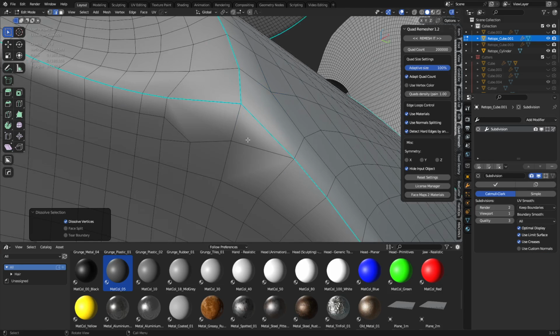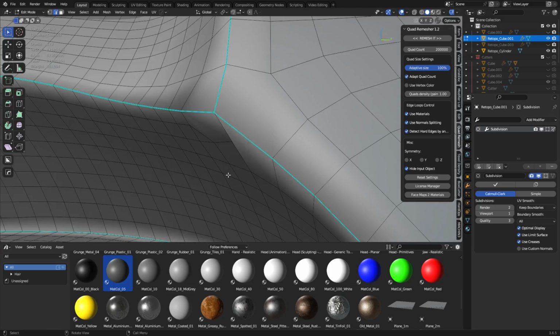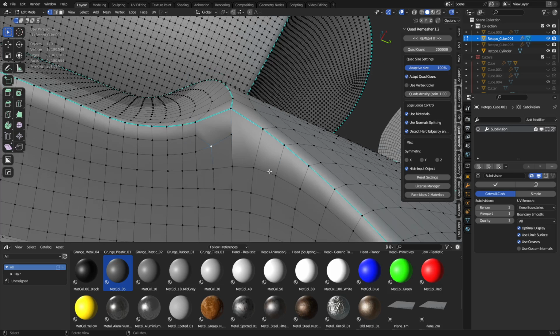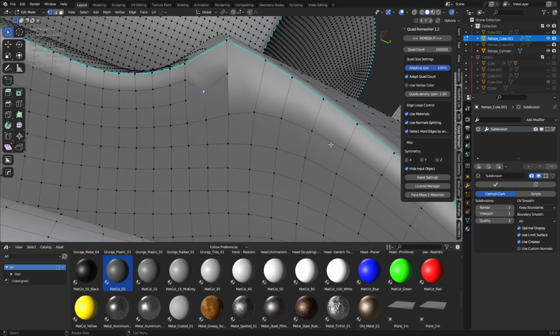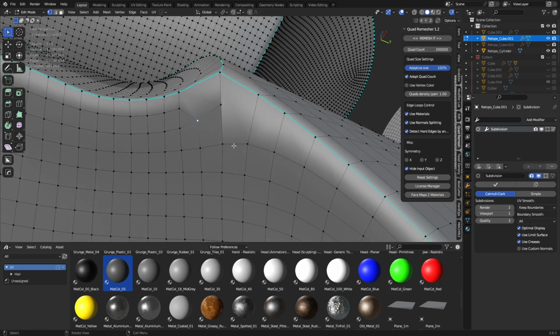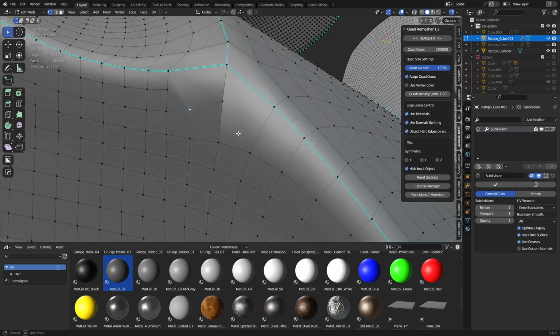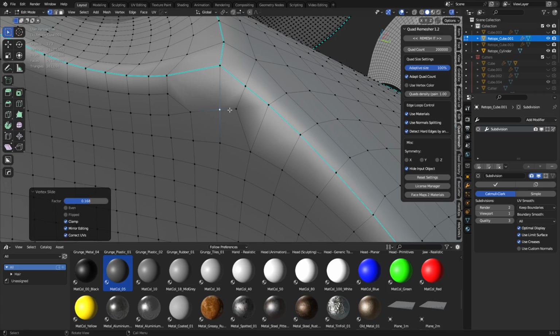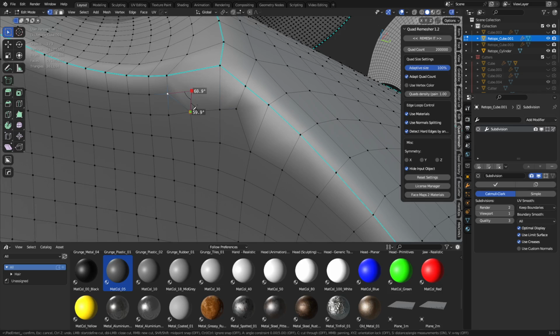We may have to clean it up more and dissolve some things back for now, just to see, maybe we can get some better ideas by doing that, who knows? I don't see an edge that really wants to run into it other than this one down here, which is going back that way somewhere. So we could just do maybe a cut from here to here, a redirect down to that way, and now we've got that going on, that's good, so those are all quads in there. We could try doing a cut from here to here and doing a redirect to there.